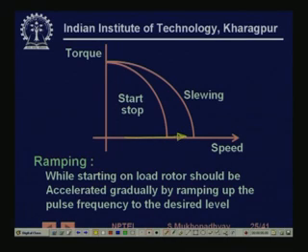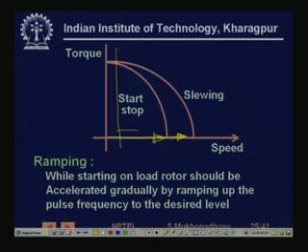And you will find that its speed is increasing, and for starting a motor you need a larger starting torque, right. So, for starting a motor you have to start from a low value and then gradually ramp the pulse frequency, but once it reaches a certain speed, then slewing will start and it has its own inertia. So it can move a certain extent by its own inertia. Therefore, you can increase the speed further and your torque requirement has also come down to some extent.